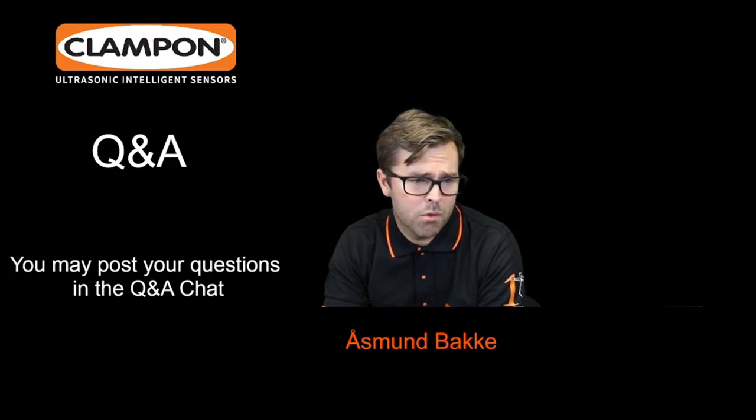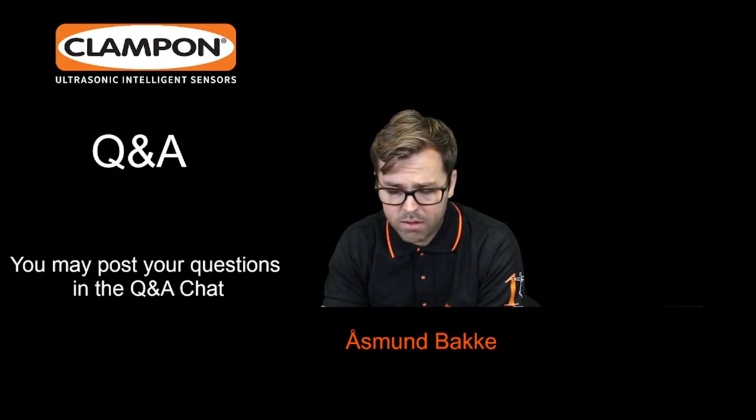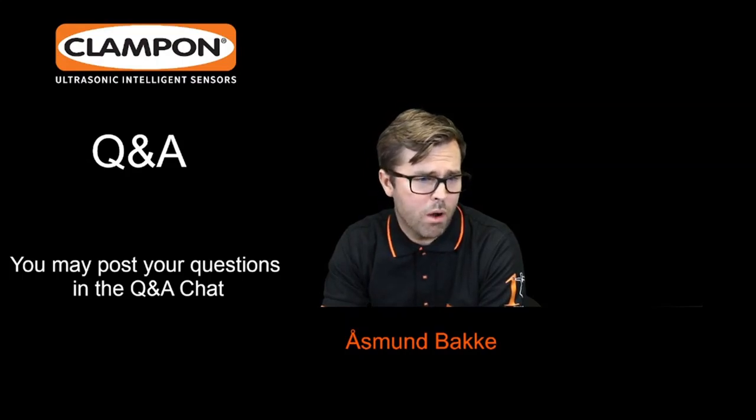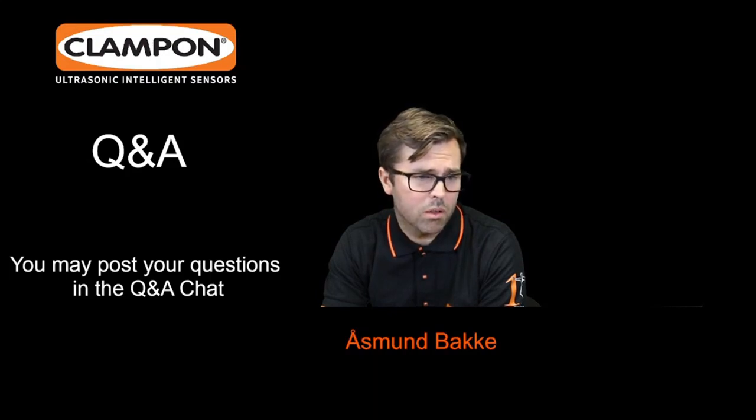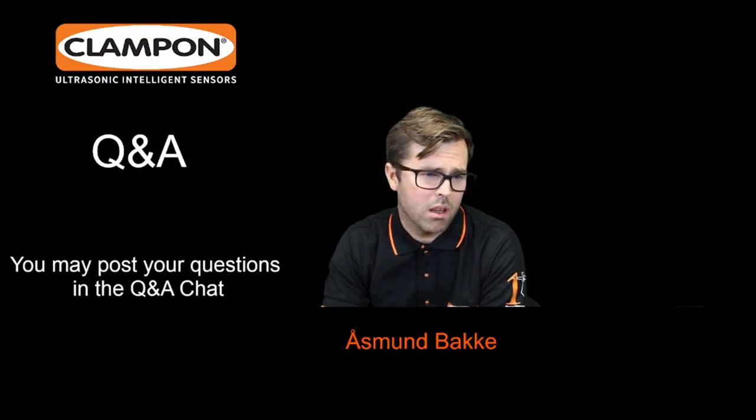And when you're taking the sand trap, you often take it for 15 minutes, 20 minutes, half an hour, etc. And very often it doesn't catch everything, maybe only 2, 3, 4% of what's in the stream. So depending on your flow conditions, maybe the sand trap doesn't get it, but also remember that the ASD may also detect smaller particles which are not going to the sand trap, etc. So normally, by having a close cooperation with the operator, we find reasons for why we detect it and it's not in the sand trap.